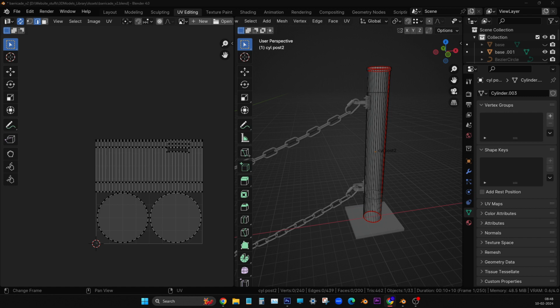Press any edge there where you want to focus. Not this vertical, horizontal, any edge. Again, you have selected vertical. Go to vertex mode. Switch on the vertex icon. Now select any vertex. Now press dot on the keyboard. Now you can work. You can maximize it. Control space. Now it will be easy for you.